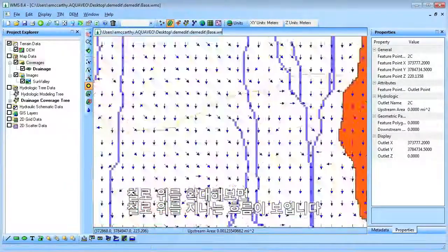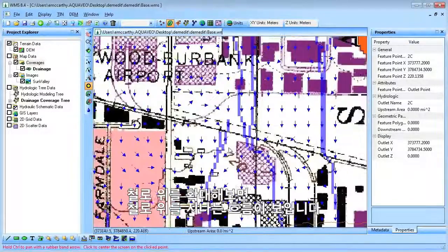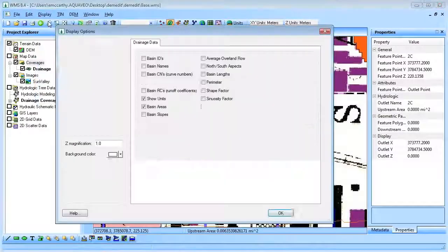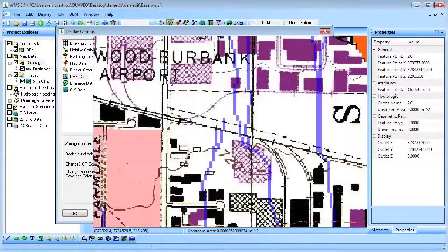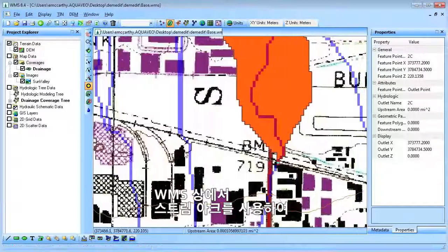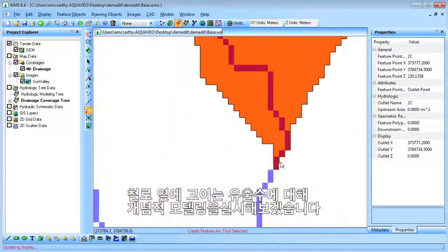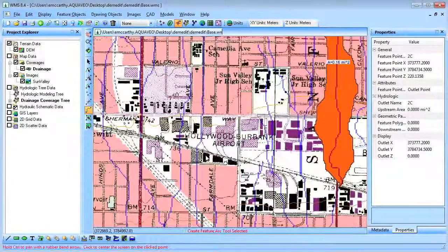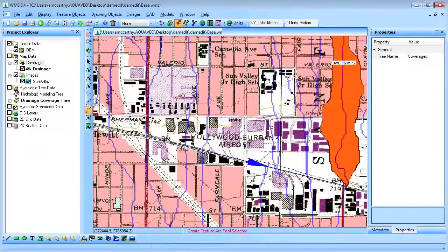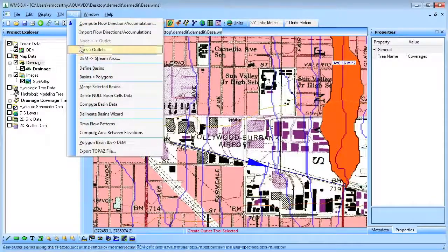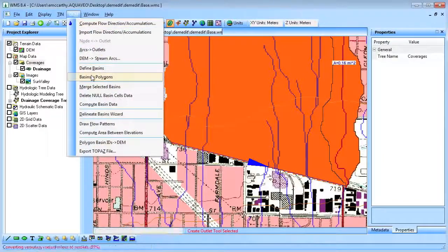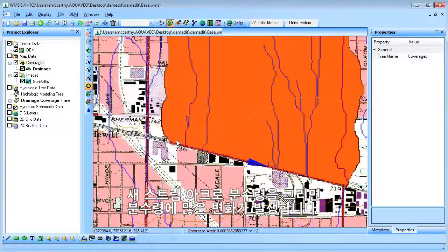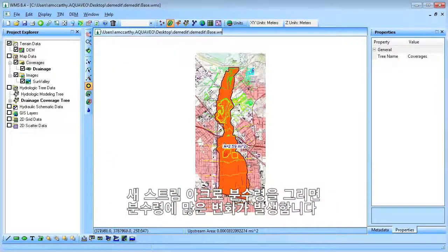By zooming to the railroad tracks, we will see that the flow travels across the railroad. In WMS, we will use a stream arc to conceptually model runoff collecting along the railroad tracks. We'll then delineate the watershed with the new stream arc. Doing this changed the watershed drastically.